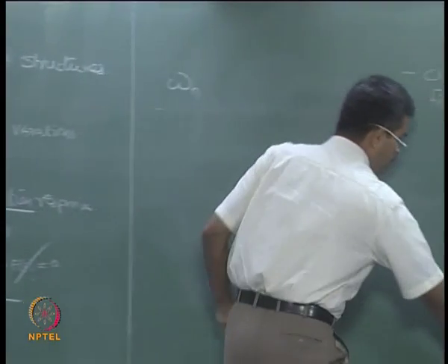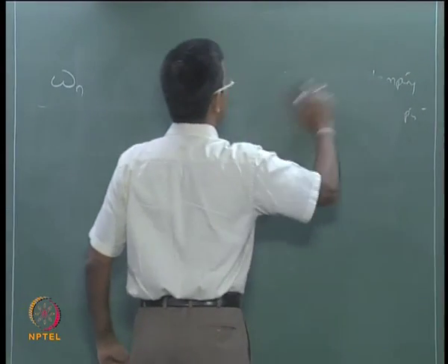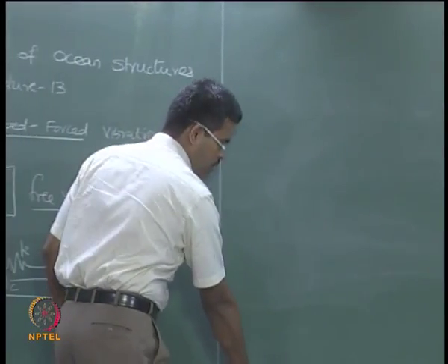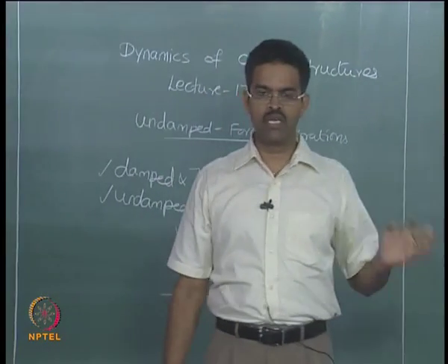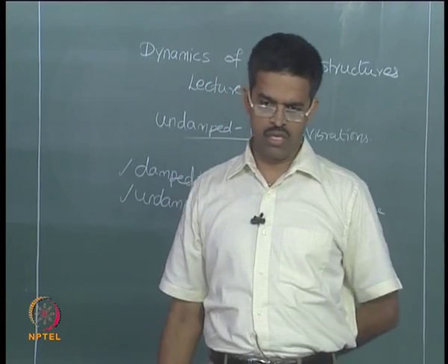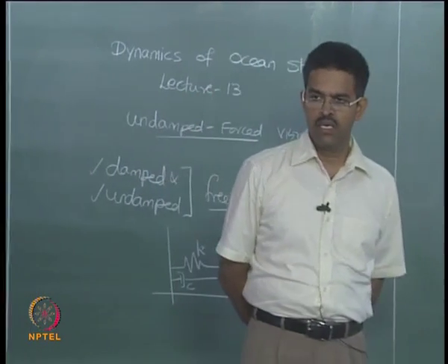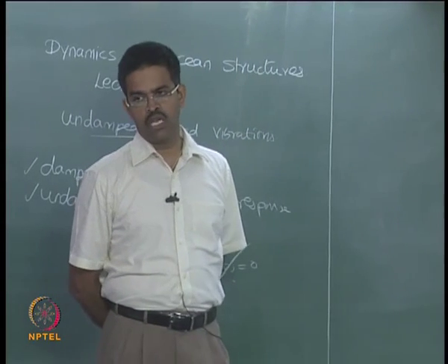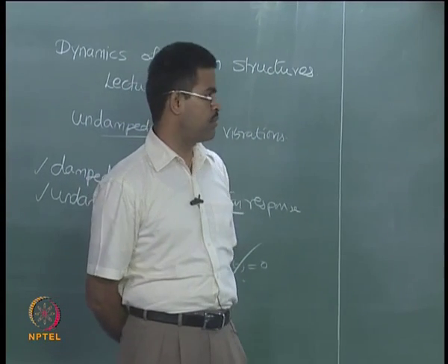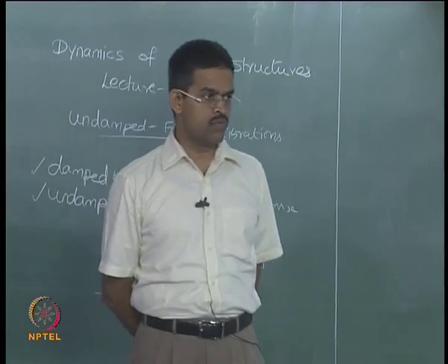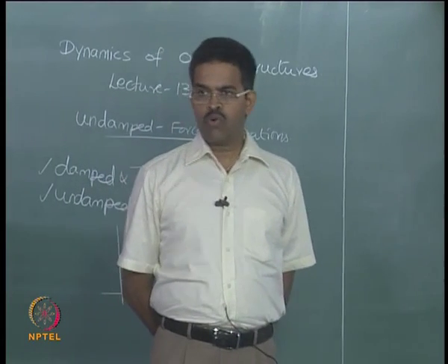Now, we will take up an external force also acting on the system. So, the source of external loading we already saw in the previous lectures, it can be from the wind loading, it can be from the wave loading, it can be current, it can be impact load from ice, it can be hydrodynamic loading, it can be also sea floor movement, it can be from the earthquakes, it can be from the large displacement because of the erection forces etc.